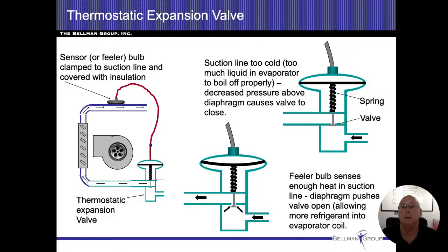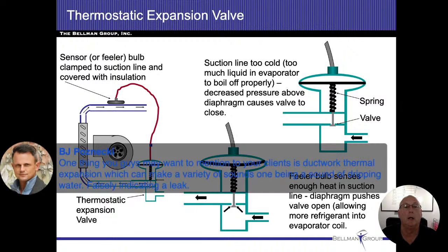Let me see here. All right. One thing you guys might want to mention to your clients is ductwork thermal expansion, which can make a variety of sounds, one being sound dripping water, falsely indicating a leak.